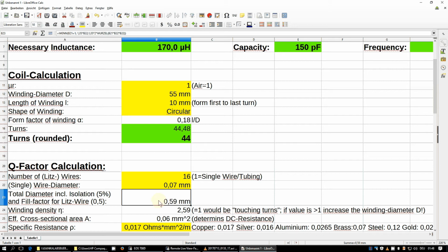And there's another thing. With these special spiral wound or spiderweb coils, for taking into account or calculating the external proximity effect, remember that because there is an uneven number of slots, that means only every second turn is again on the same side.